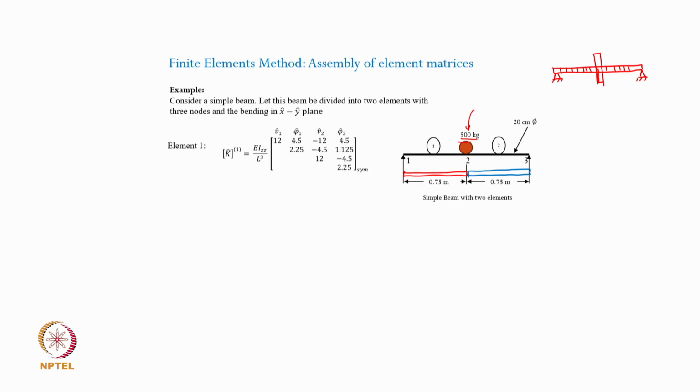But having discussed this, we again go back to this finite element stiffness matrix, which is a function of the material parameters and the cross sectional dimensions. So, when the shaft is vibrating or going to bend in this vertical plane, if these represent the coordinates x and y in the xy vertical plane, if it vibrates, then for the bending vibrations, the area moment of inertia is going to be about the axis z, right.